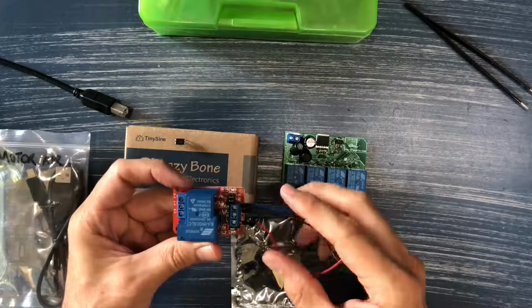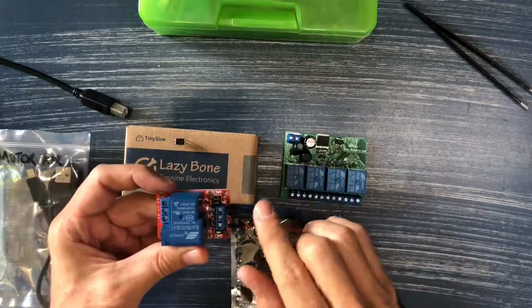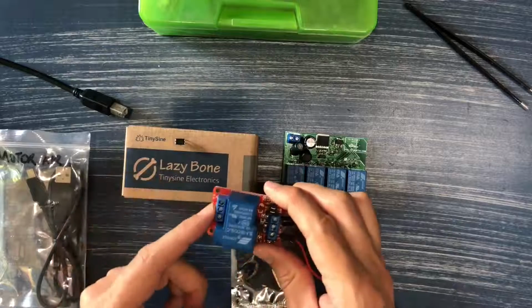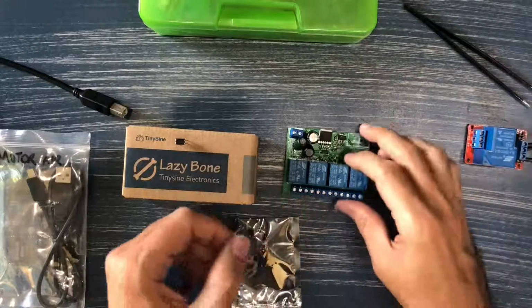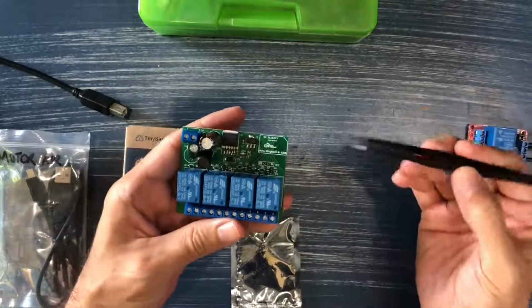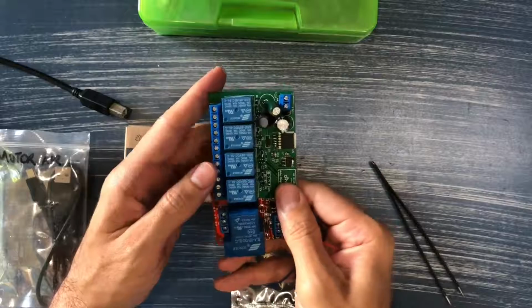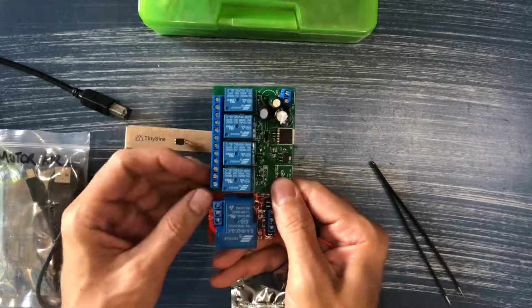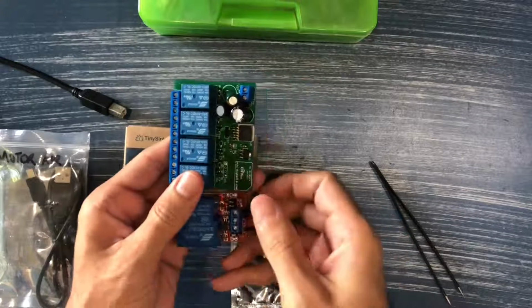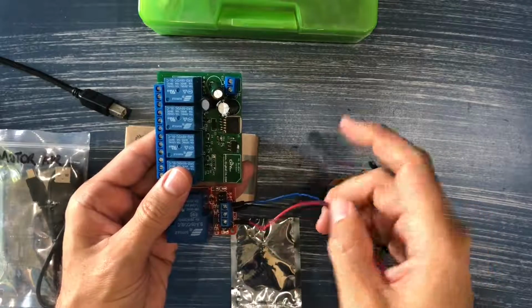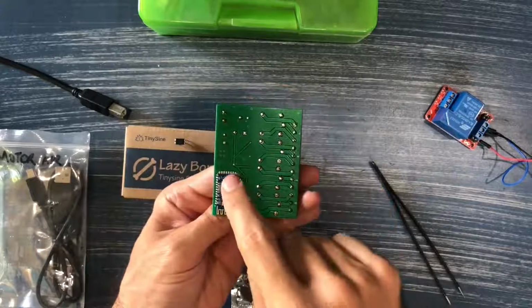So in this case, we saw the relay, and it had a low side, which was the 5-volt DC, and it also had the high side over here, which is where you connect it to the object you want to control, the actuator. In this case, the first difference is that there's actually 4 relays instead of just 1. But if we line this up, the high side, here's a relay, and there's 4 of them on this board, but the high side is over here, which is like this high side, where you connect the lamp or the motor. The low side, which is the one you're going to control digitally, in this case, there are no cables, as you can see. It's over here.